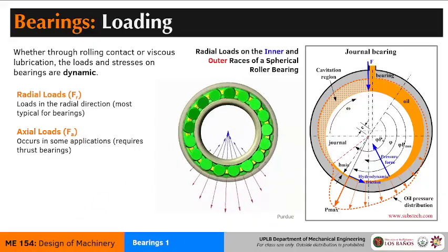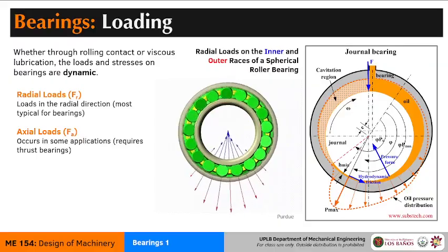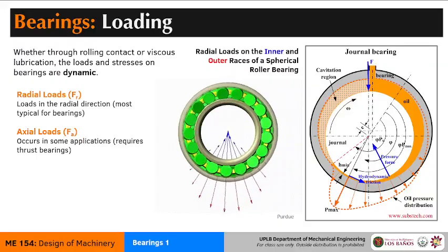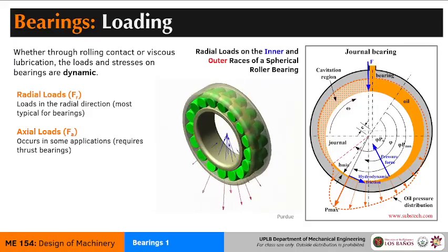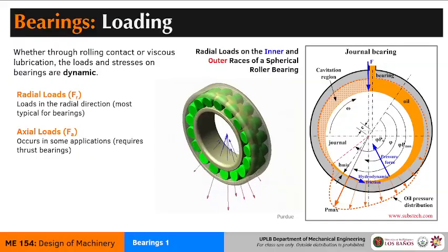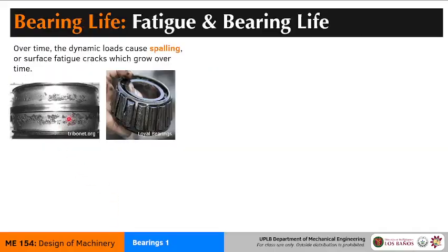All right. So if these are the loads, what does a bearing running out of life look like? When a bearing starts to reach its operational lifespan, its design lifespan, it will start to have little pock marks. We call these spalling in the bearing subfield. You can have these little potholes, kind of like substandard concrete roads that we see all the time.